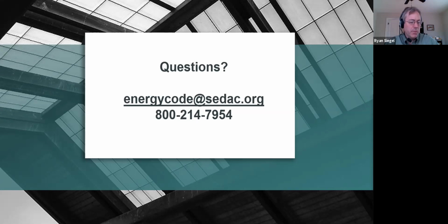But that is definitely something we would encourage people to use. Commonly, we will get people asking how much cavity insulation can I use to get away from having to use both continuous and cavity. For this question, we would definitely encourage people to consider increasing the continuous insulation on the outside. Again, you eliminate all of the thermal bridging that you would necessarily have with the combination insulation method.